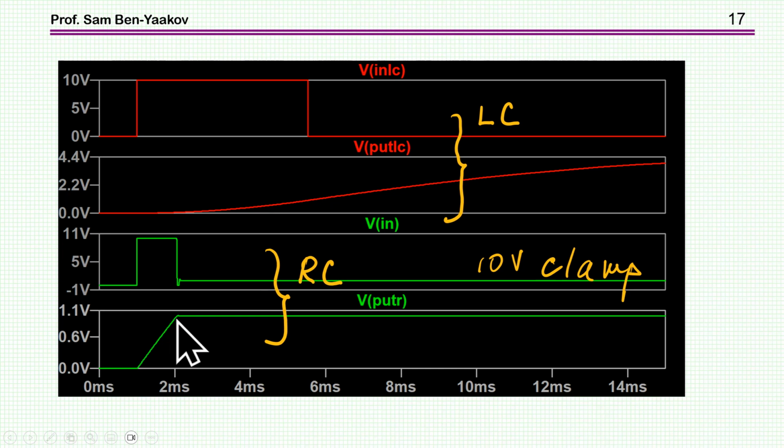So we see that limitation, in this case a clamping of a voltage, is really changing the behavior. And this is in fact what we call a slew rate. That is, a nonlinear behavior causes a given slew rate to the system, which is not related to the equations that we have seen before of a second order system.